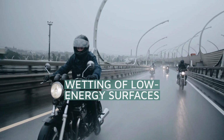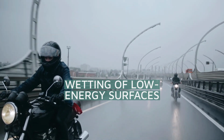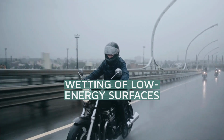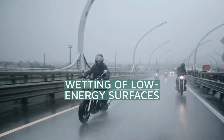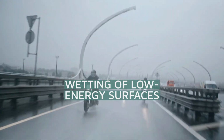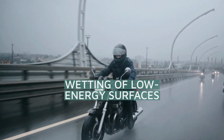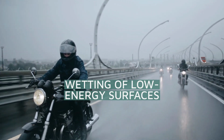Wetting of low-energy surfaces. Low-energy surfaces primarily interact with liquids through dispersive van der Waals forces. William Zisman produced several key findings. Zisman observed that cos theta increases linearly as the surface tension gamma LV of the liquid decreased. Thus, he was able to establish a linear function between cos theta and the surface tension gamma LV for various organic liquids. A surface is more wettable when gamma LV and theta are lower.